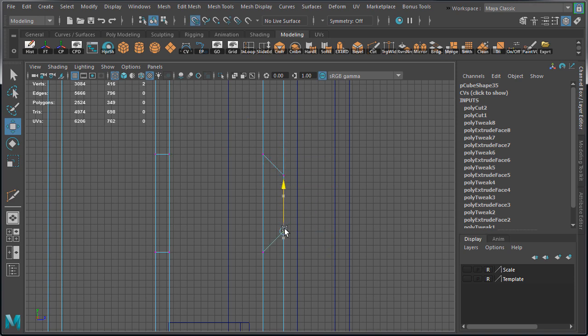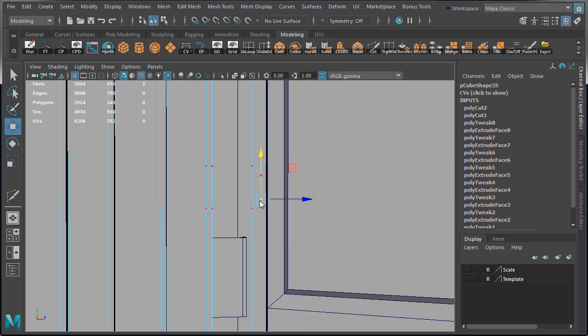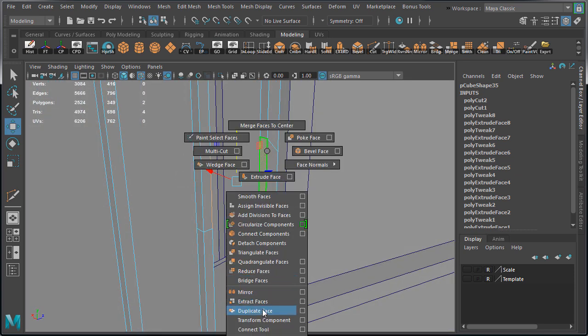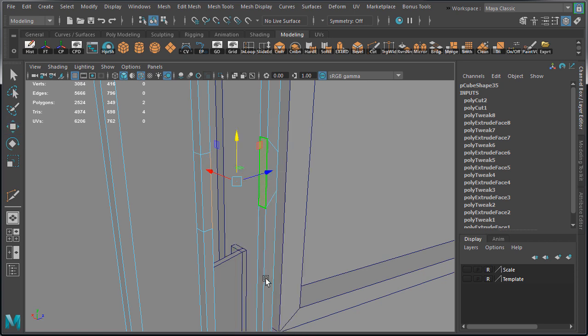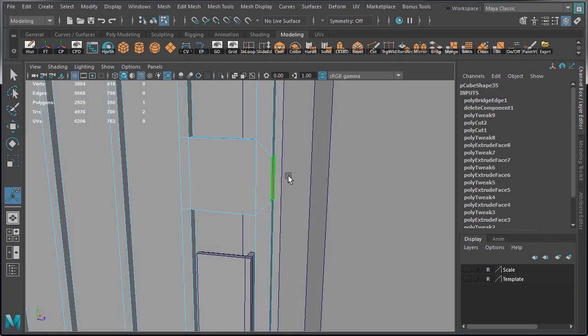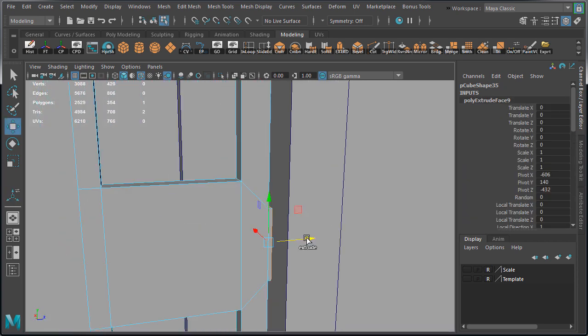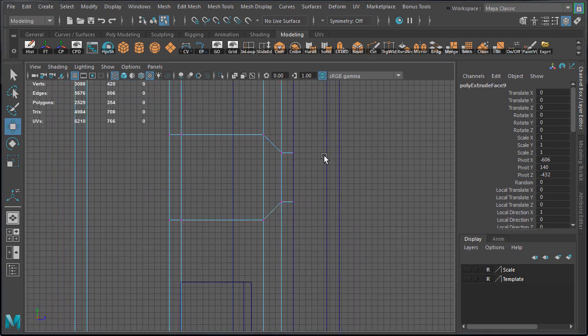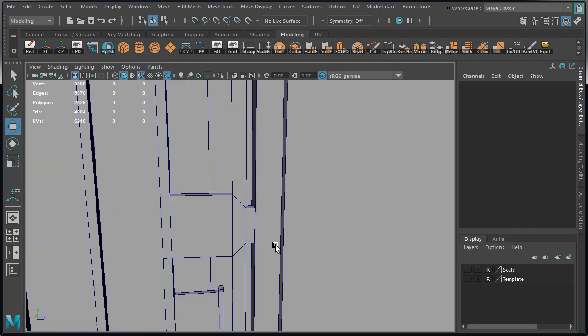and then grab these two vertices in the front and move them in. Let's go to Perspective Viewport, switch over to Face Component Mode, select these two interfaces and bridge them, and then select this face and extrude, making sure we snap to the inner door frame. And here we have our geometry for the lock.